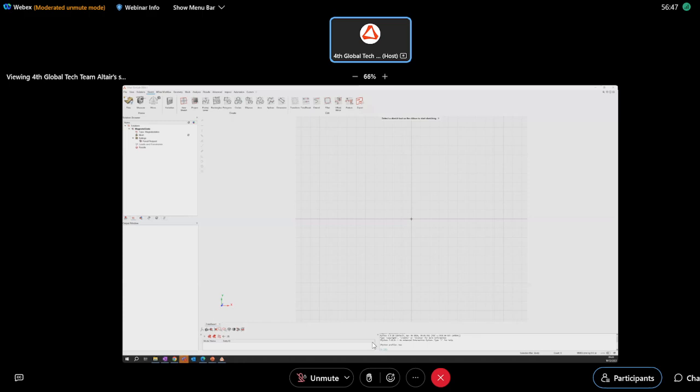And to create the wire, we can use the circle by center and point tool here. Clicking on it, you can just move the cursor and put a point along the x-axis, for example. When you position the cursor right, you can see a reference of the position. So you can enlarge and create a point along the x-axis. The point should be positioned at 10, 0, but it doesn't matter. Don't worry, because we can change the position later.